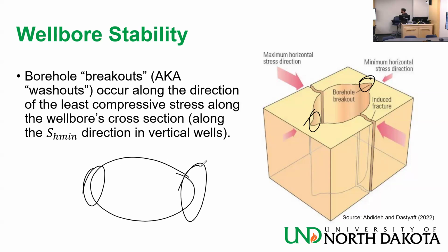This is basically washouts, or borehole breakouts, or wellbore washouts, whatever you want to call it. This is the washout. This is when the wellbore pressure is smaller than what it needs to be. It's just before a kick is about to happen. You get a washout. If you keep doing it, becoming more and more extreme, you get a kick.